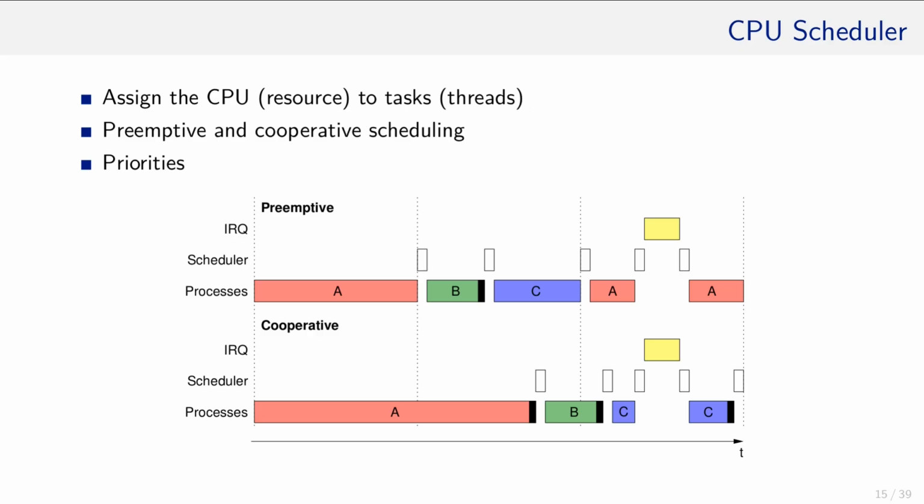Imagine that one task is waiting for some resource. Instead of polling the state of the resource, it could say, maybe later again, and give control to someone else. That scheduling will work if the tasks play fair and nice, and no task is hogging the CPU, either due to malicious intent, by forgetting to release the CPU resource, or since it crashed. In this case, the watchdog timer could be of help by causing an interrupt, allowing a scheduler to check the health of the current task.